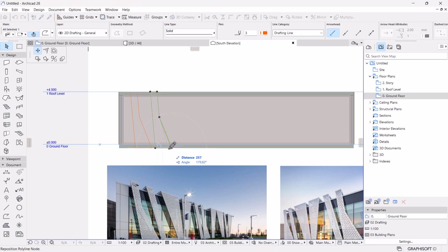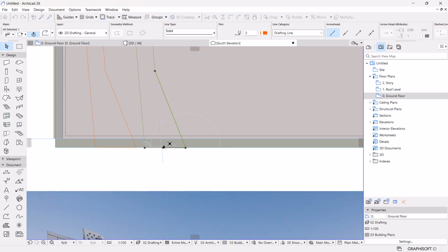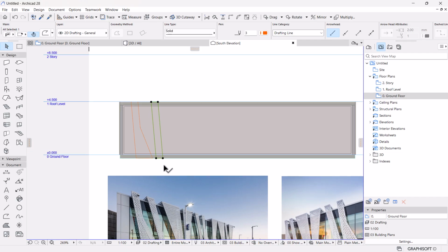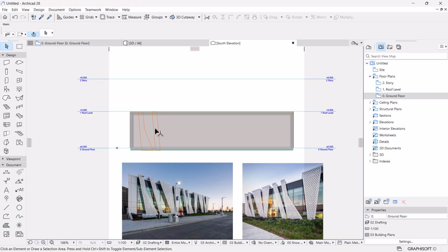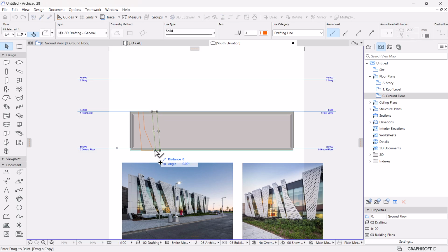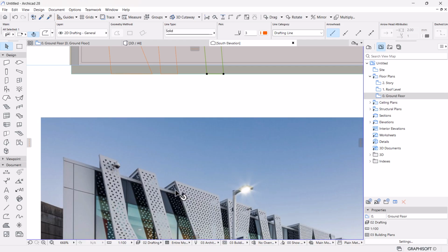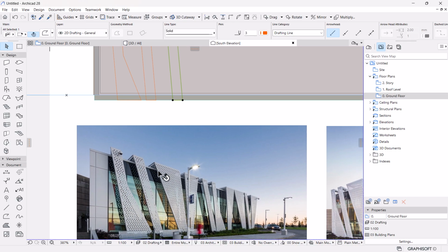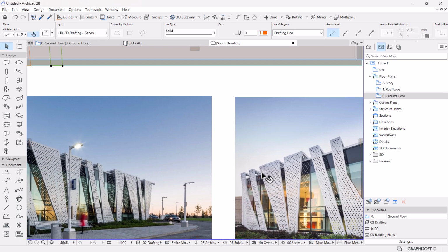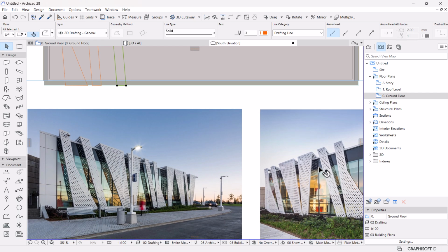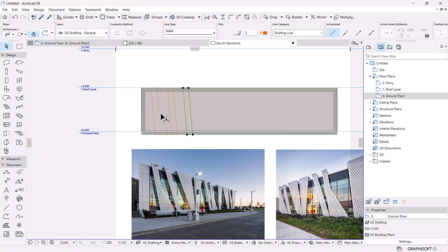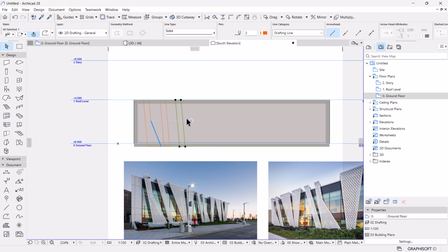And we can bring this one to there and then get rid of this point like that. Okay, let's select this, Control Shift D again to make a copy. This time around, I'm gonna create a space of 1 meter. Do you think the spacing looks the same? I don't think it's the same. Okay, for the sake of the video, I will have to estimate, but don't crucify me for that.